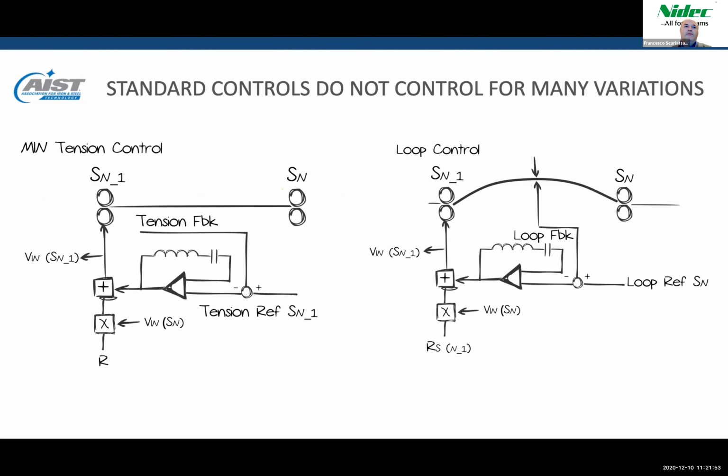We have two other feedback loops that are used to achieve consistency by controlling the tension on the product. The consistency is done in the roughing mill by the minimum tension control and in the finishing mill by the loop control. These feedback loops achieve their regulation by adjusting the speed of the upstream stand. In most cases, we care about those now. The cascade control constantly adjusts the target speed of the stands based on information it receives from the tension loop and controls to keep the mill synchronized.